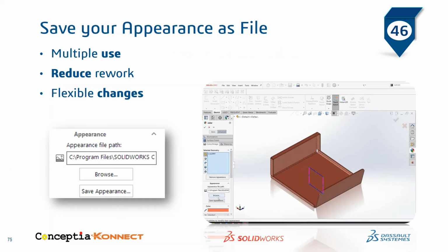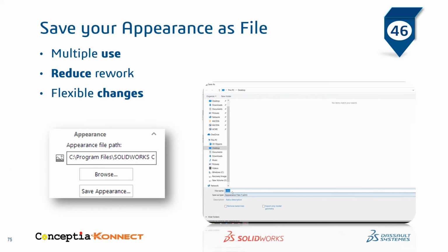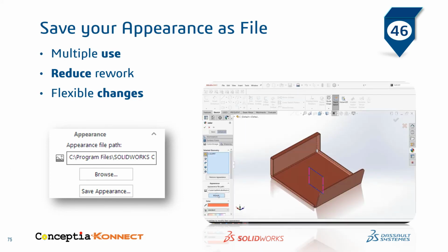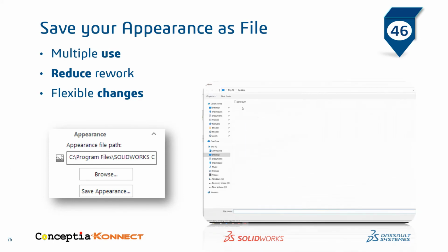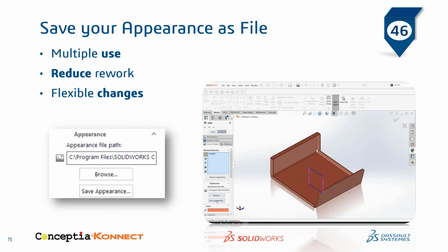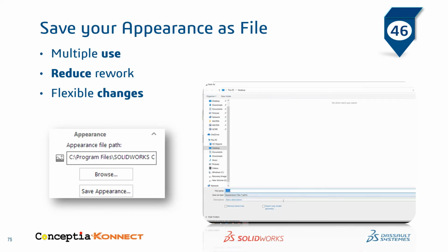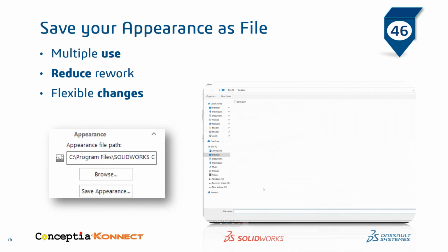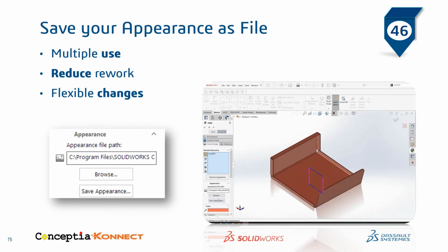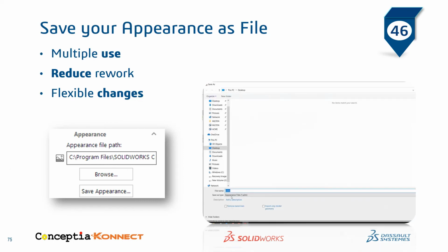Number 46, save your appearance as a file. It's not your 3D data as you do traditionally. It's your appearance property which can be saved with Save Appearance option, and you can use it in multiple areas to avoid rework.